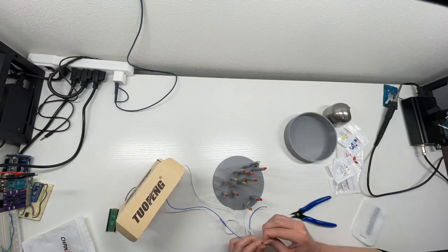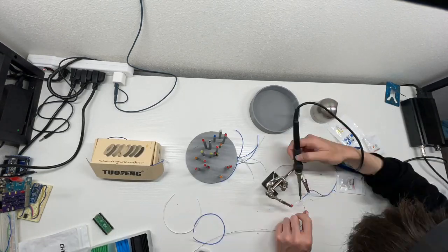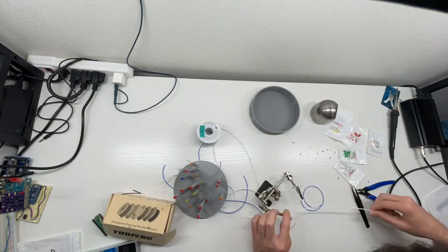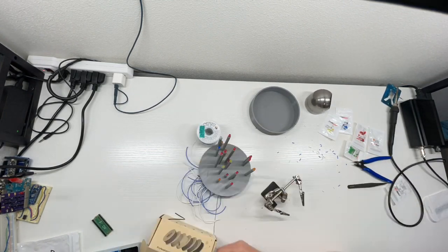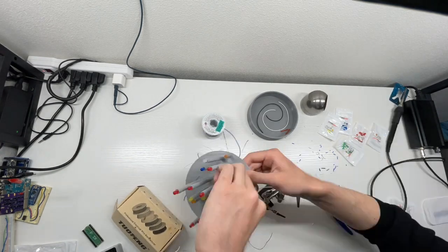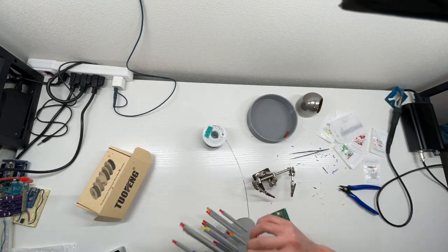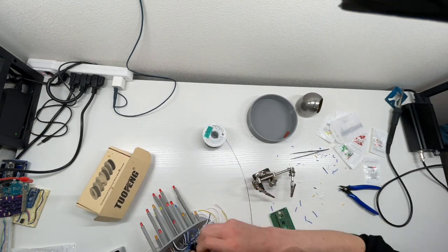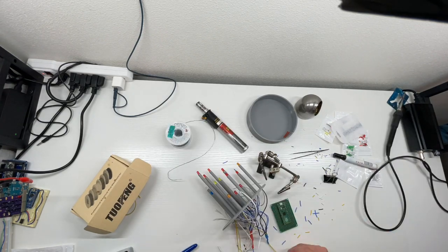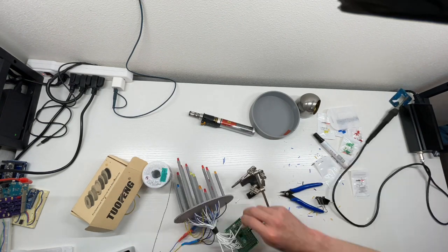After 3D printing, the spectral types of each of the stars were referenced and an LED corresponding to the star's spectral type was chosen. Long wires were soldered to each of the LEDs and heat shrink tubing was used to ensure the leads wouldn't contact each other and short. The LEDs and their wires were threaded through each of the cylinders. Optionally, all of these LEDs can be connected to a Raspberry Pi Pico or other microcontroller, which can be used to flicker the LEDs on and off at random to create a twinkling effect.